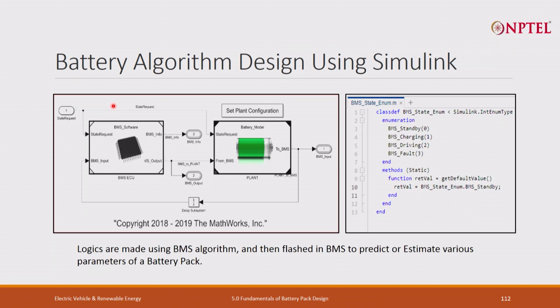Then you can write scripts and check all the functionality on the software, which we call software in loop simulation, and can generate the C code which can be directly fed into your BMS.